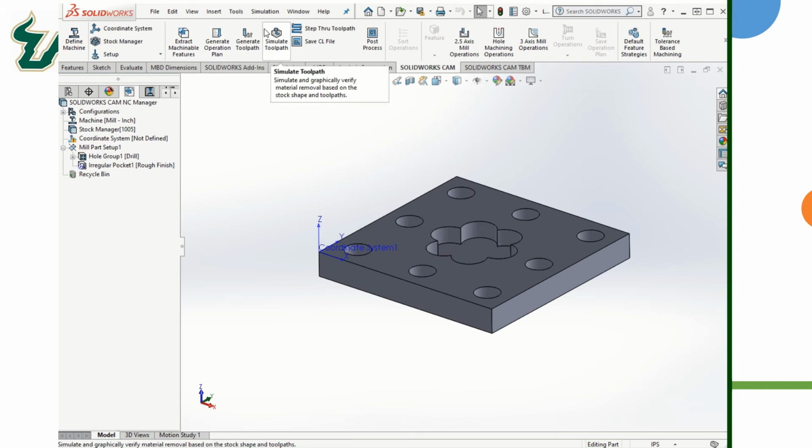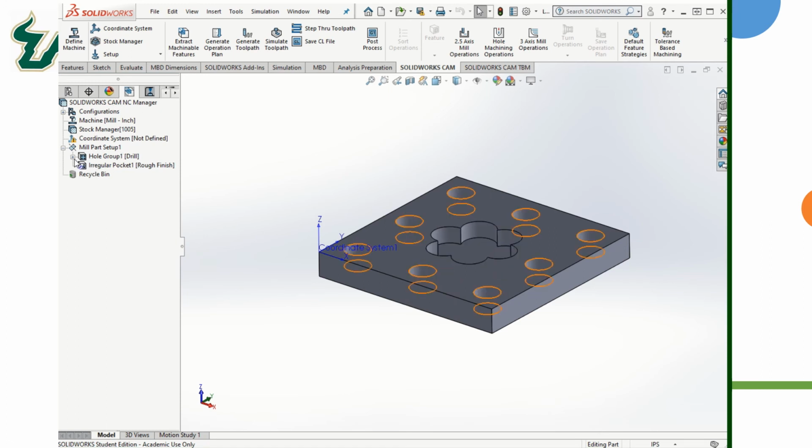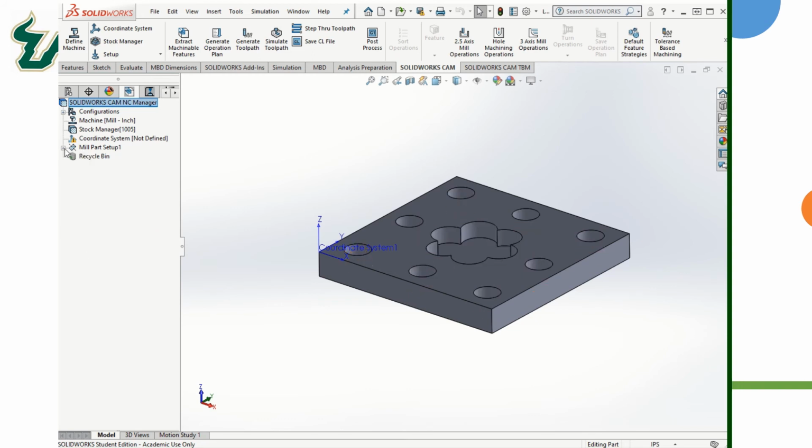All right. Then we've got generate toolpath, and obviously it generates the operation plans automatically for the selected machinable features. The operation plans and the associated parameters are generated based on the rules which are again defined in the TechDB. The operation contains information on how the machinable features will be machined. Okay, and the operations generated in this step are listed in the feature manager window under this CAM manager tree here. Those were the different holes, as you can see there.